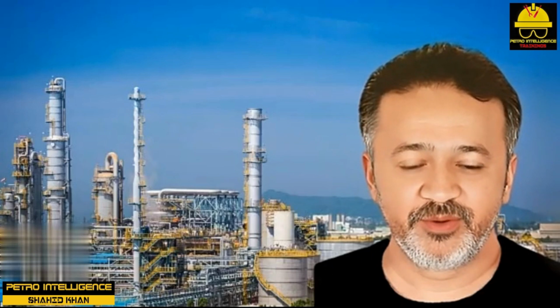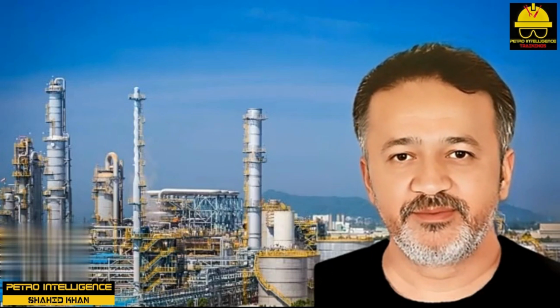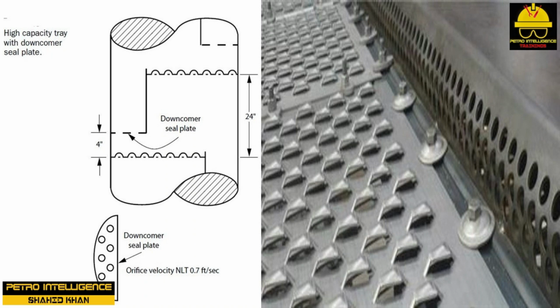But what keeps vapor from blowing up the downcomer? What prevents loss of the downcomer seal? If the downcomer seal is lost, surely the downcomer will back up and flood the upper trays of the column. The design of this type of tray is the Norpro high-capacity tray shown in the picture. The head loss through the orifice holes in the downcomer seal plate shown is sufficiently high to prevent loss of the downcomer seal. These trays flood rather easily when their designed downcomer liquid rates are exceeded.